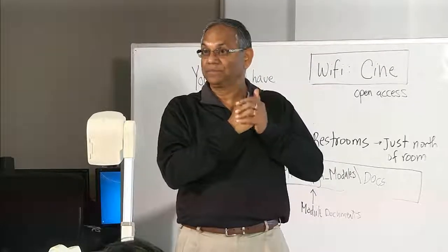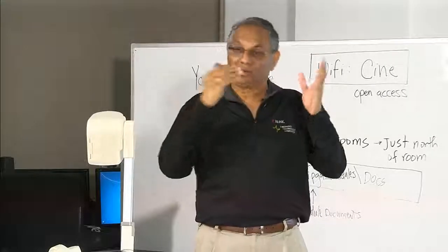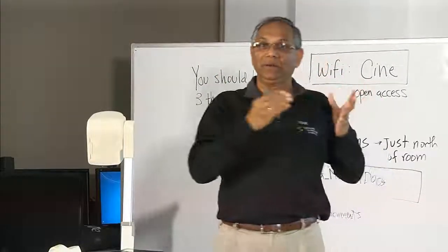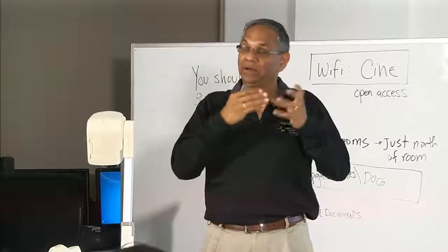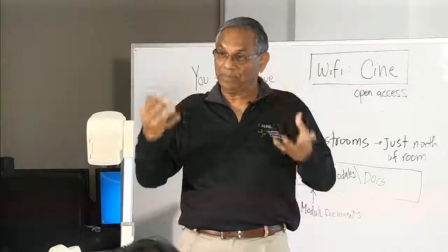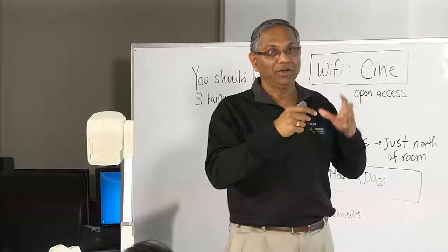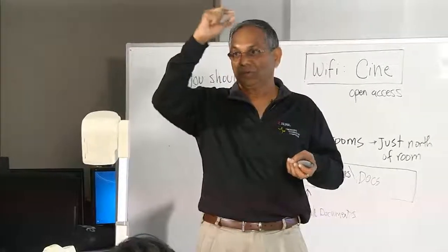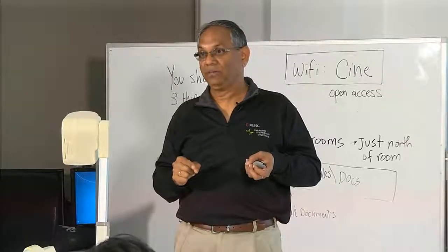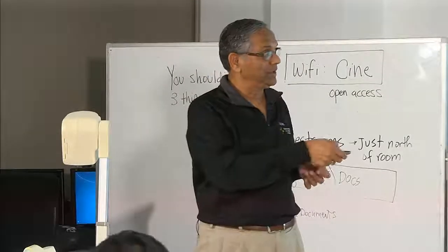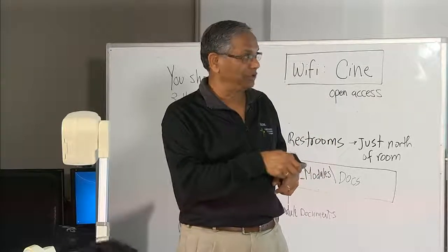So the lookup table is not just combinational, it's combinational plus. You can visualize it as if it's sequential. So the question was, the lookup table is not just combinational, but it's combinational plus something. And yes, it can implement or can act as if it's sequential. Okay, so you can think of 32 small flip-flop bits connected in cascade form, and you get the 32-bit delay here. Okay, so it's 1 bit output either at Q32 or Qn.